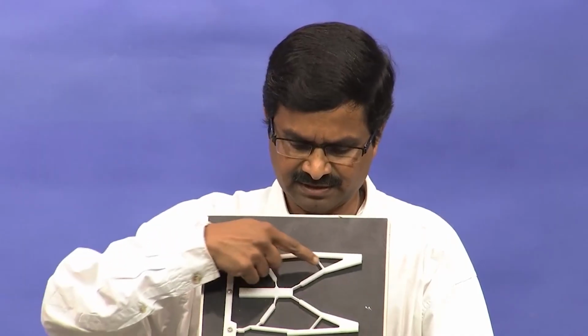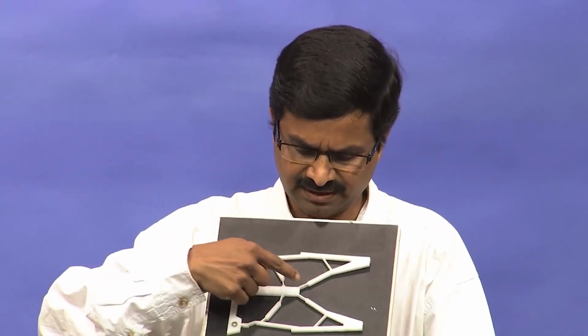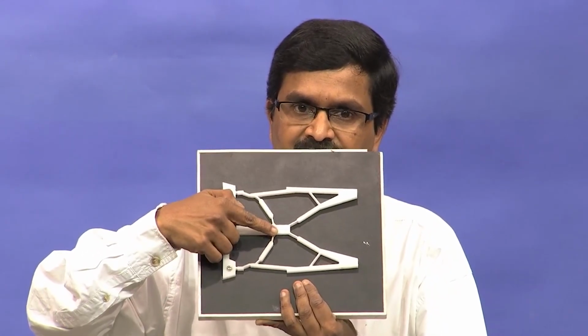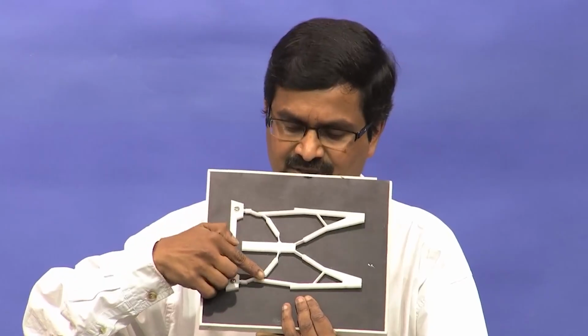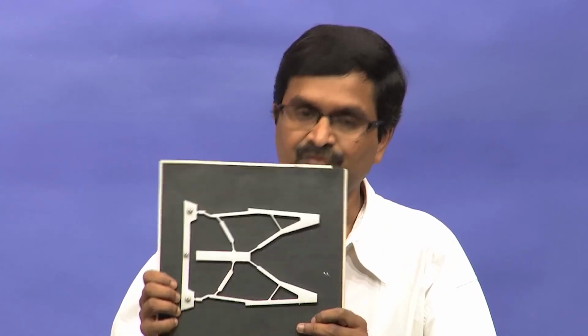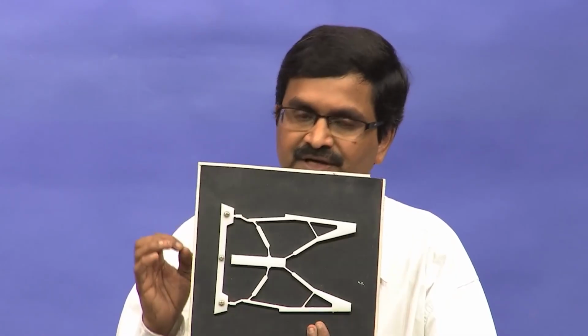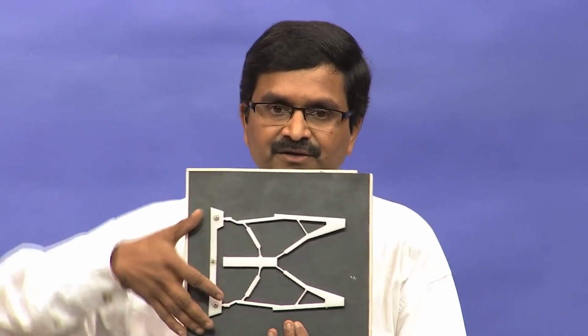elastic pairs or joints which connect relatively rigid portions, meaning that if I look at this segment, it has an elastic pair here, this is rigid, and if I look at this one, there is an elastic pair here as well as down here. So, there are elastic pairs, meaning joints that connect. It is still a monolithic mechanism, or what we call a fully compliant mechanism, but it has these elastic flexures which give it a discrete compliance, and you can see how it works.